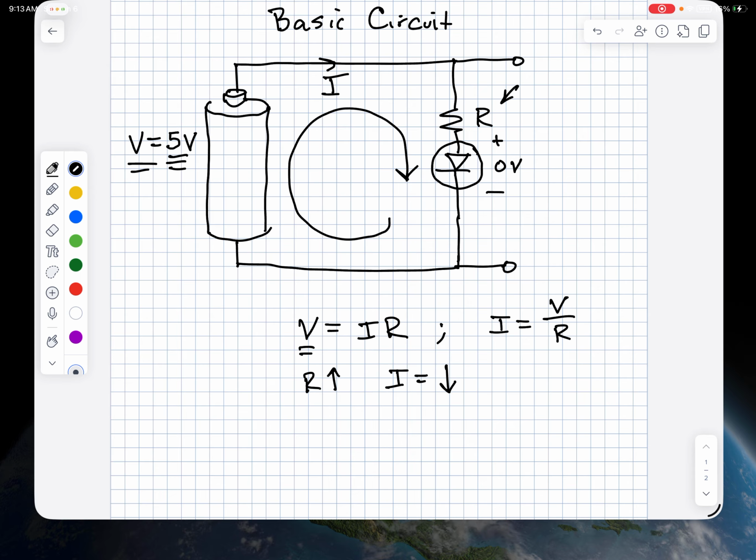So you might be asking, what's the function of R? Well, if you have an LED circuit and you just put R equals 0, you'll get essentially infinite current, because V divided by R with R equals 0, the math predicts infinite current. It wouldn't actually get to infinity because it would blow up the diode and smoke the diode. So the reason we have R in this little simple loop circuit is to keep that from happening.